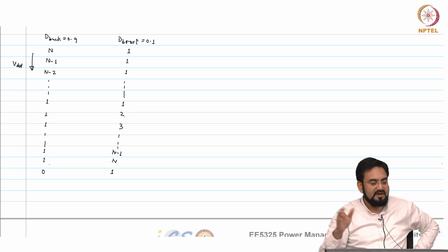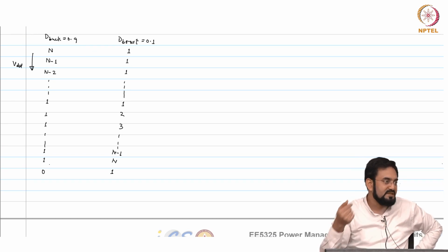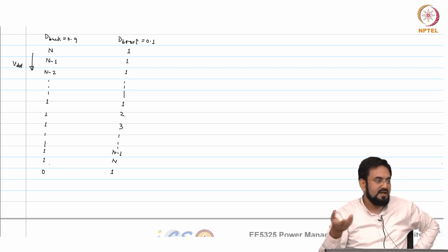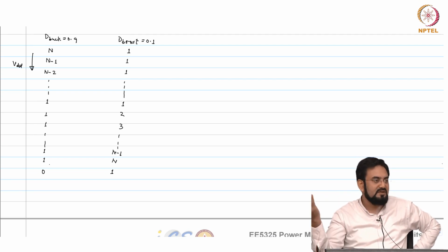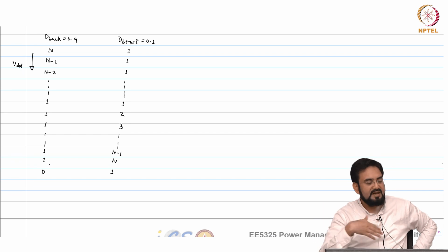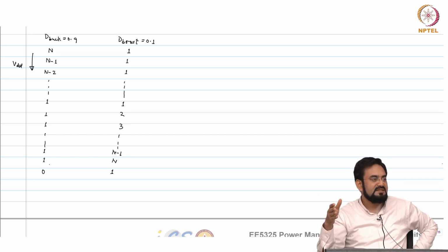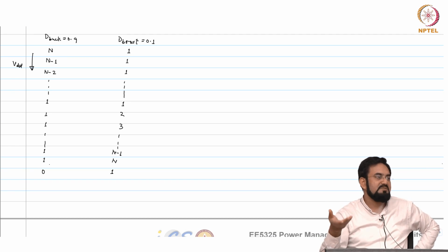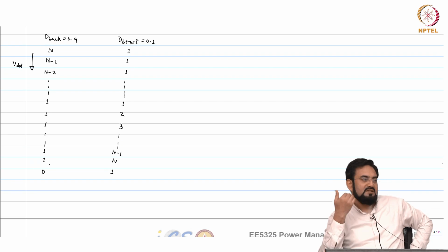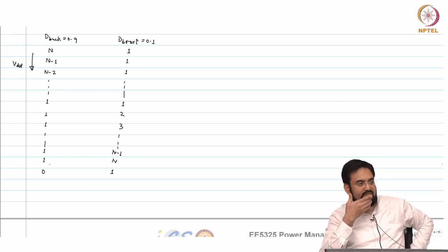You do not need to always limit at 90%. It could be in some cases 95%, it may be 94, 92%. It all depends, you have to run across PVT and see exactly what is the maximum duty cycle where your circuit does not respond, and you just limit your duty cycle on that. From that maximum we can directly jump to 100%.